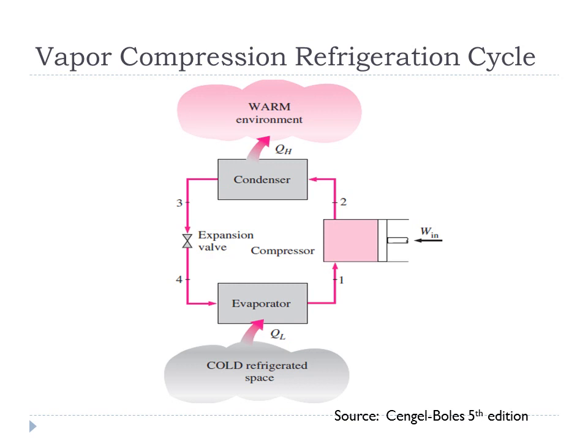At this high pressure and temperature, the refrigerant vapor enters the condenser, and in condenser, since the temperature of the vapor is so high, even higher than the temperature of the environment, because of this temperature difference, the heat QH is rejected to the environment, and the condenser, as the name implies, condenses the vapor of the refrigerant ultimately into liquid phase.